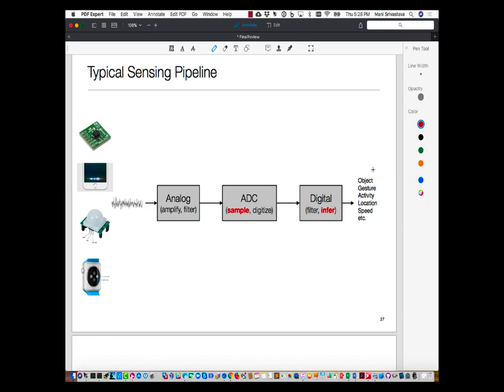So compressive sensing made use of the fact that we may have additional knowledge about the signal. In particular, in this case, the signal is sparse in a parameter domain. If I look at that signal in frequency, amplitude and phase, then it's extremely sparse. So we're making use of that fact, and compressive sensing builds upon that idea. So that was the second one.